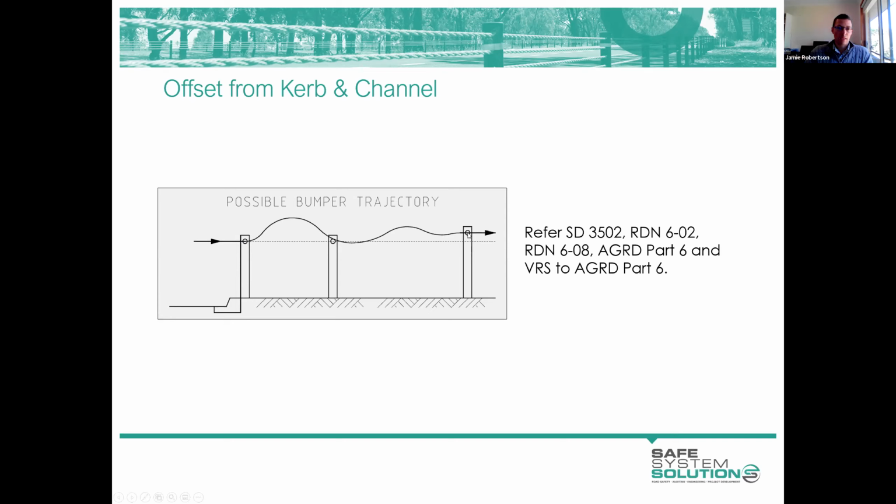It's rarely the case where you've got curb that you've got 7 metres or more to play with. If you've got curb, you're probably in a built-up environment. So you've got footpaths and trees and poles and things in the nature strip. Or if you're in a rural environment, you've probably got a curb because you're in a cut, and a cut batter in here somewhere. So you usually don't have much room to play with, and this is where we choose to locate our barrier.